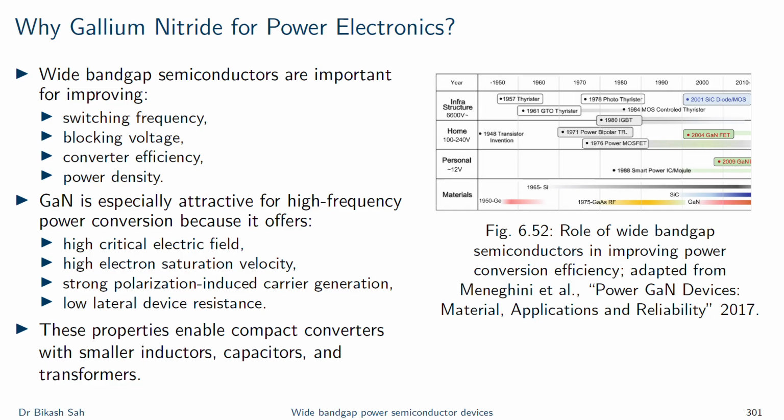But you should remember that these advantages are not automatic. They appear when the gate driver, layout, packaging, thermal path, and EMI strategy are all built together in a very constrained, coupled environment, to get the best benefit out of the complete GaN power converter.